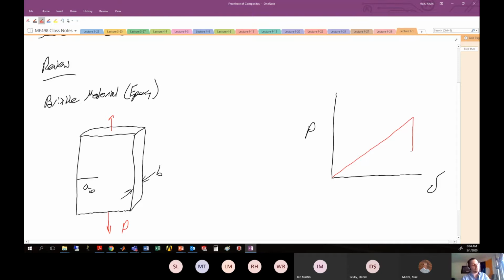Okay, so we have this fracture event, and that fracture event is going to cause this crack to propagate from where it is to some further distance down the line. And we typically denote this additional length as delta A. Right? So right before the crack, we have this value here, which is something like delta F comma P1. And after the crack, we still have that same displacement, assuming we're in displacement control on our load frame. And here we're going to have the same displacement, delta final, and this will be P2.